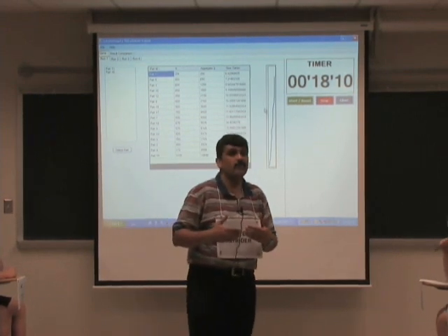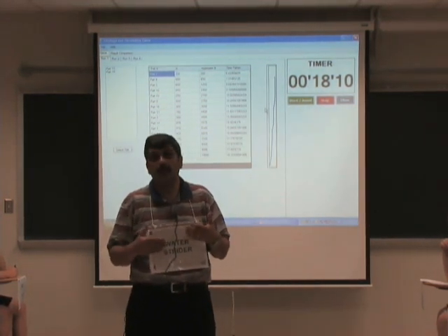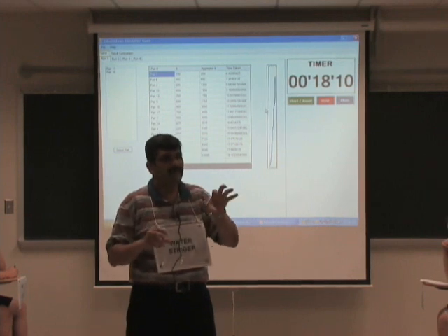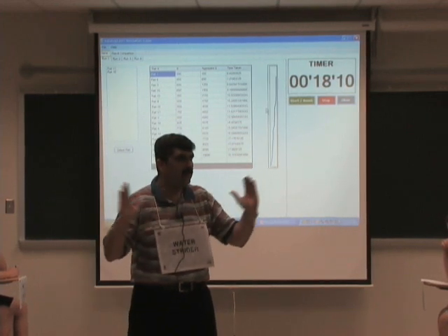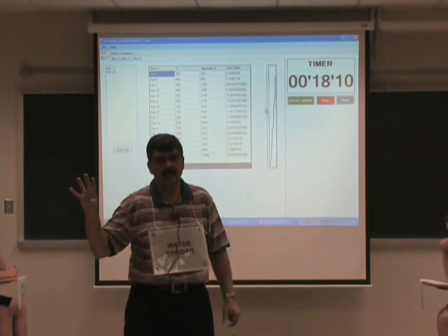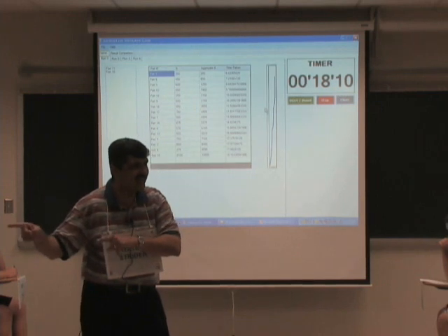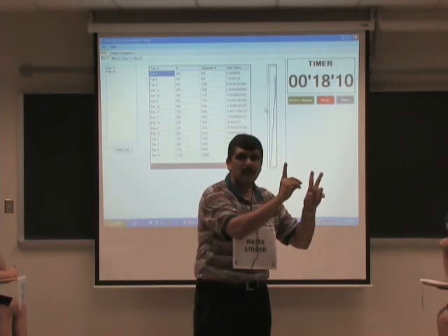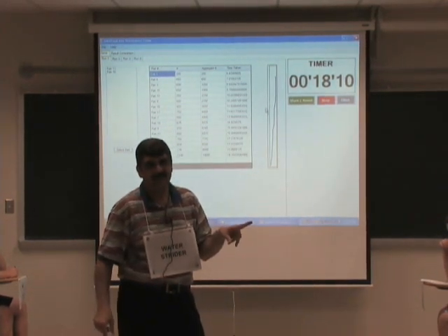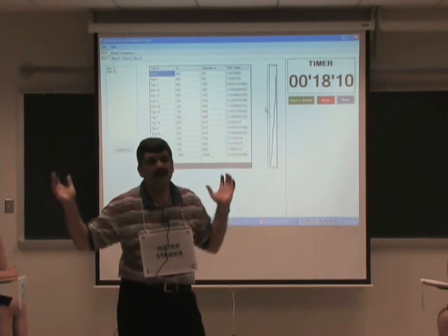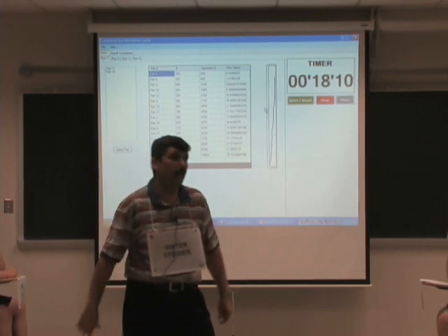And so what you might want to do in the future is, hey, can I have a hybrid? So if we have time, I'll show you the example of something called a modular layout. This is where you have fractional cells. So there is a movement, but the modular layout is in between the process layout and the cell layout. It's much more flexible than the cell layout, not as lean as the cell layout. But it's much more lean than the process layout, but not as flexible as the process layout. Because in the process layout, you pretty much say, I can do anything you give me. In the modular and the cell layouts, you're not as flexible on the mix of products you can produce.